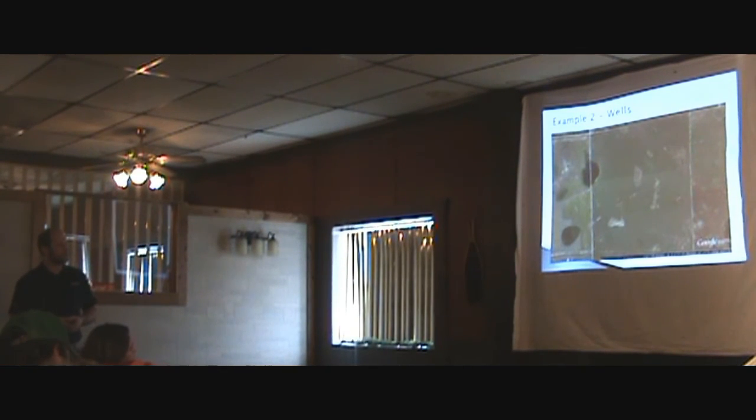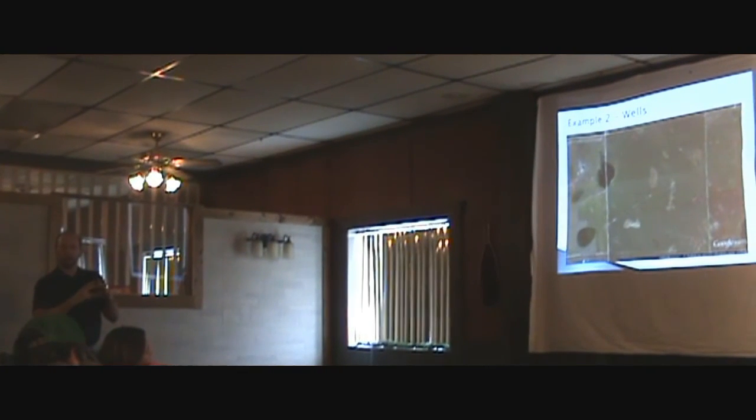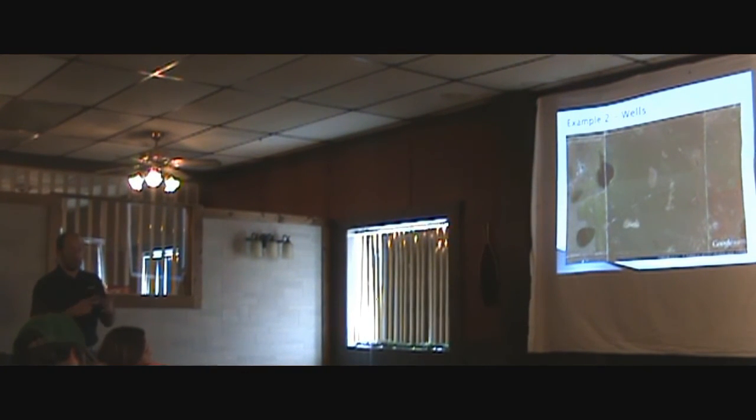electrician installed a simple pressure switch system on these 3 wells down here. They put in a little PLC computer that monitored the pressure switches, or the pressures, so as the pressure started to go up, it would start kicking off these pumps here, 1, 2, 3. Without that, the pressure was going up to 100 pounds, which was way beyond the point of safety, so we obviously had to do that.